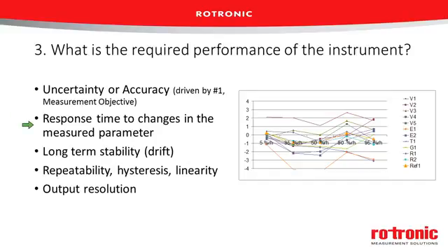Another thing that we might need to look at is the response time in our instrument. As Bruce mentioned, depending on how stable our environment is going to be, we may need something that has a very fast response time. Another factor in response time would be the filter that's over any sensors. Different filters will also impact the response time of the reading. So we need to be careful about what filters we choose. And we have to understand that some filters are going to make that response time grow longer. And does that cause a problem for us?